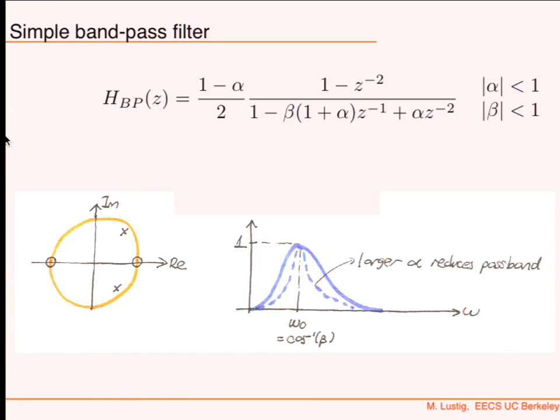Okay. So when you have a system of 2 zeros and 2 poles, then it has that kind of Fourier transform. That is the form of the z transform of the transfer function. That just comes from the fact that you have a second-order polynomial at the bottom and a second-order polynomial at the top, and then we just normalize it by this parameter such that the magnitude at the frequency of interest would be 1. Okay, so this is just a normalization.